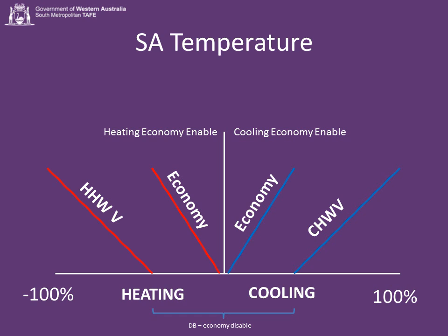If outside air isn't available for heating, then once again my deadband just becomes bigger. I'm pretty sure I spelled economy incorrectly there, on economy disable. It's too late to change it now. Anyway, my deadband just becomes bigger. Once again, I'm just saving money.